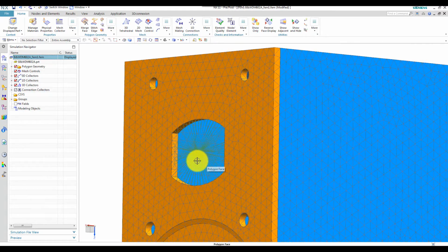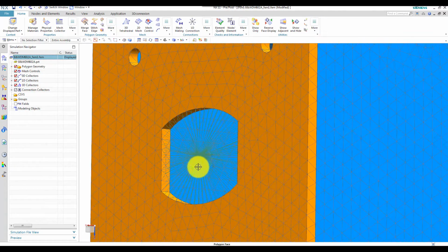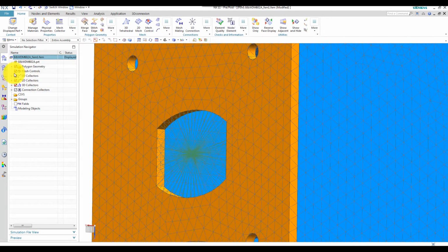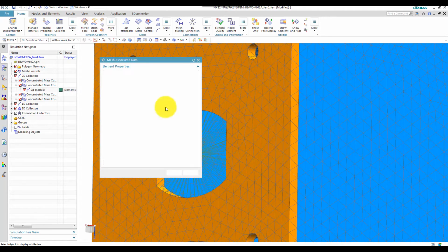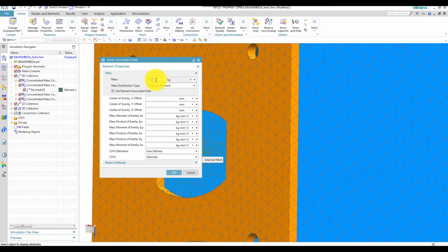There was one resonance frequency that was still too low, which, based on the mode shape, told me that I have to strengthen this area or reduce the mass. Let's hope that it's enough to reduce the mass, and imagine that we can find a tweeter which is not that heavy. The first one was 0.5 kilos.